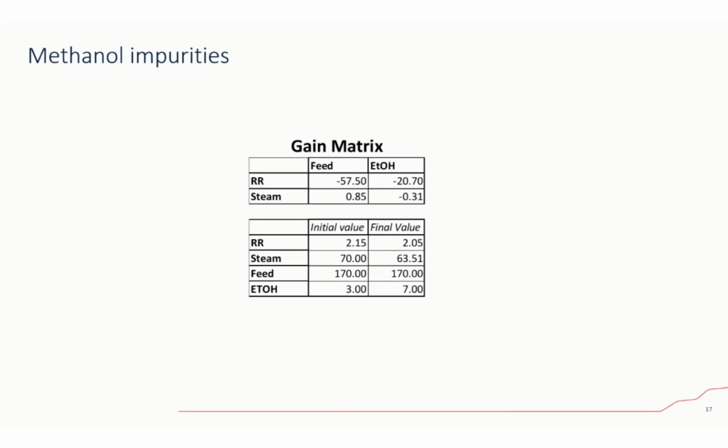If there are correction movements during the time the steps are being done, that typically gives you not so accurate results. What you get is a kind of closed loop response. I wouldn't say it's a closed loop response, but at least I can tell you that your process gains will most likely be underestimated. So these automated step testing tools should be used with care in these complex columns because of time to steady state and interactions.